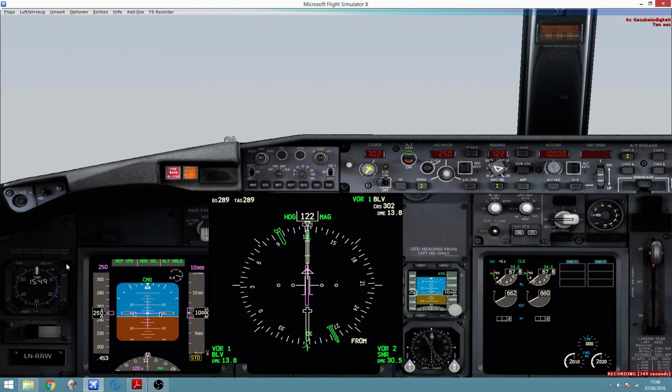Here I have a chronometer that I will start. I can start the chronometer by pressing on the top left corner of the chronometer here with a finger, and this needle will stop moving. This way I can count for 60 seconds, and then once I am done with the 60 seconds, I will turn by the left towards the VOR of Bravo Lima Victor. How will I know where the Bravo Lima Victor VOR is? Well, by looking at the thin arrow.